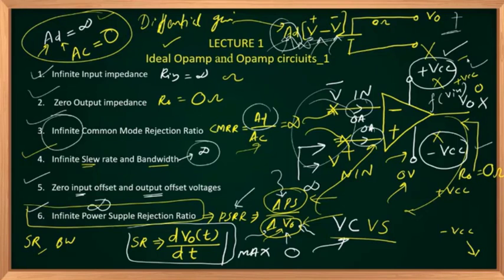Let us say plus VCC is slightly going up or coming down. This is a VCC line. If my supply is increasing from VCC, my output should not change. My output should change only with respect to my input signals. So I'm expecting a zero change at my output based on a change in the power supply line. Is that clear? It's just a definition, that's it.